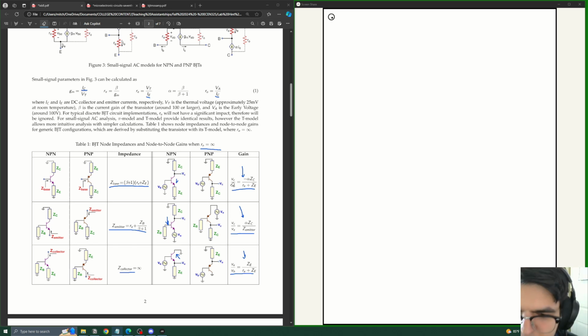And it's very common that we will take these amplifier configurations, these BJTs, and chain them together, usually for some purpose, and usually one of those purposes is simply to achieve higher gain. We'll put multiple of these common emitter stages together to get a much higher gain. So let's look at a pretty common case, where we have a common emitter.